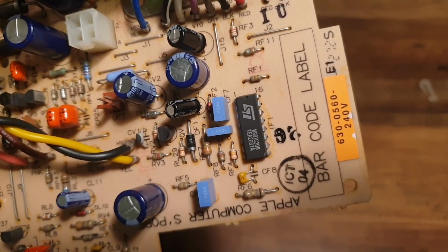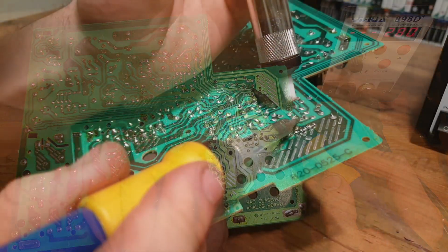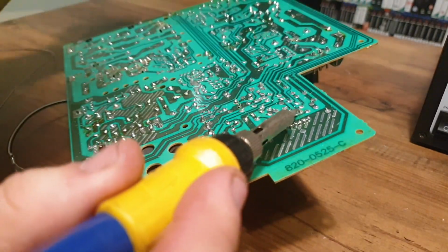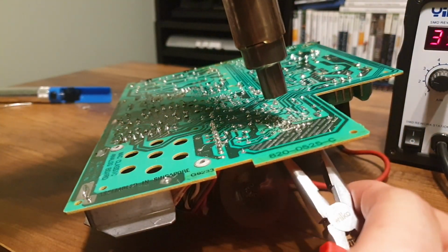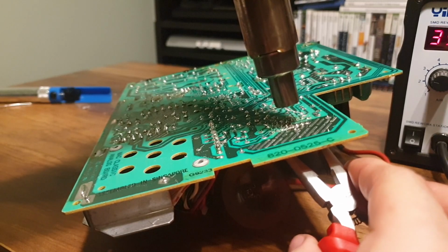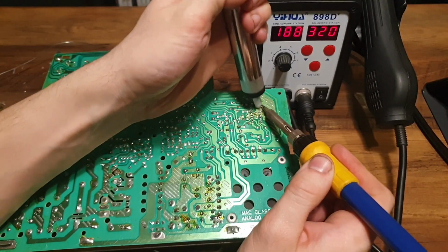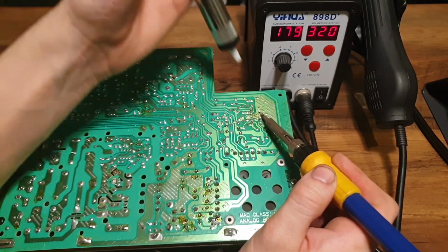Removing the TEA chip is fairly easy as the analog board is single-sided. I just reflowed the pins with fresh solder and then used a desoldering pump to remove the excess solder. To aid removal of the chip without damaging the pads, I used Adrian Black's method of using a heat gun to melt any residual solder. Finally, I cleaned up the holes by soldering them all again and then using a pump to remove the solder to leave clean holes.